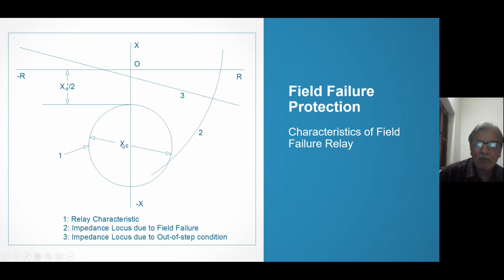And the action is time delayed because overheating is a function of time. And after that time delay, the machine will be operating in class B trip mode. Class B trip mode means we are just closing the turbine and boiler. We are not opening the generator breaker. Therefore, the machine will go on feeding power. We will utilize the kinetic energy of the machine. But then power will slowly come to zero. And before it comes to zero, the low forward power relay will sense. And the low forward power relay is a class A trip. Therefore, finally class B trip is going to result in class A.